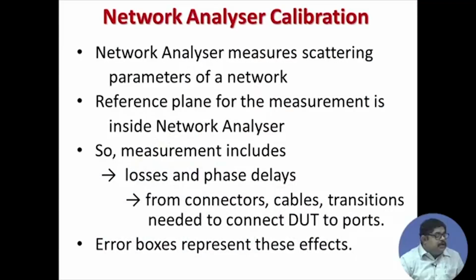So, this extra connection, connectors, cables, shifts the reference plane, and that is why the measurement includes those losses and phase delays that are obviously present in any cable, connectors, etc. And so, there is some error in the measurement.